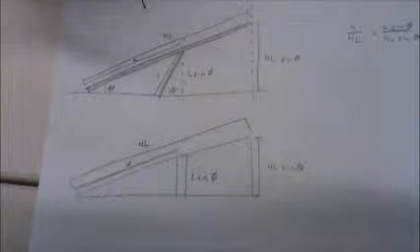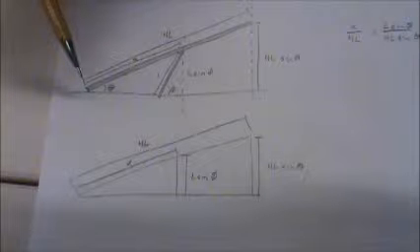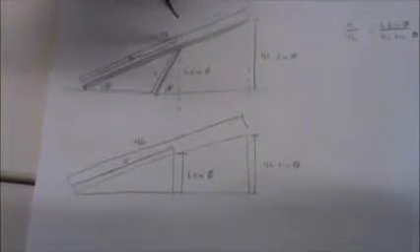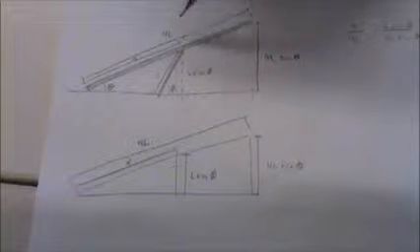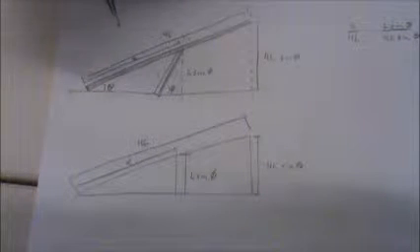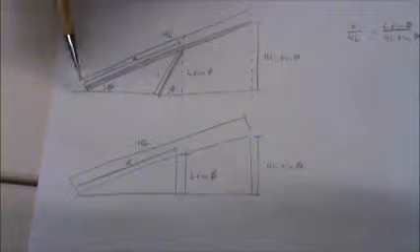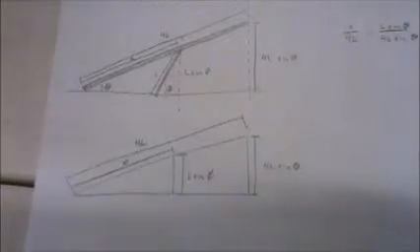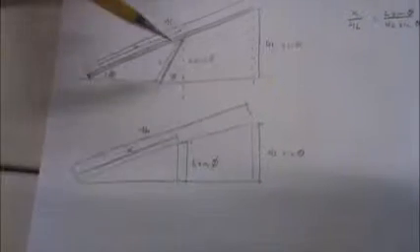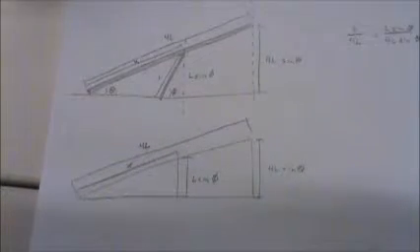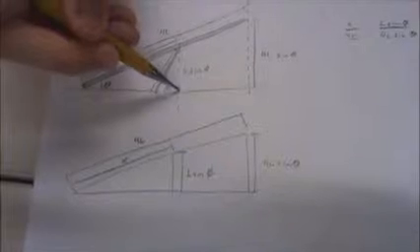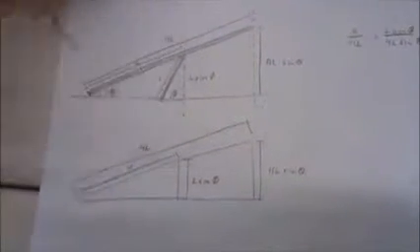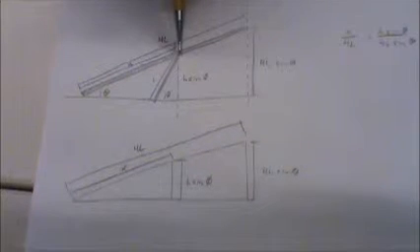So here we have a simplified diagram of how we're going to go about finding this distance x between point A and point C at the end of the second bar. This is going to be useful because it's going to tell us the length of the moment arm for the normal force between these two bars. We're going to find x by setting up a series of similar triangles. The first triangle is this smaller one here, and we're going to use this angle phi to find this vertical length. So we're going to do L times the sine of phi, which is the opposite to that angle phi.